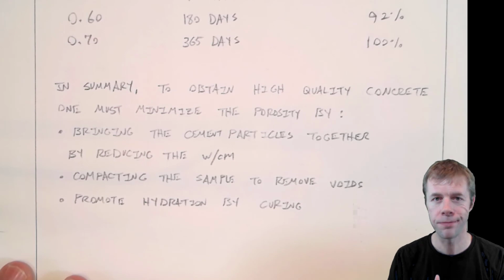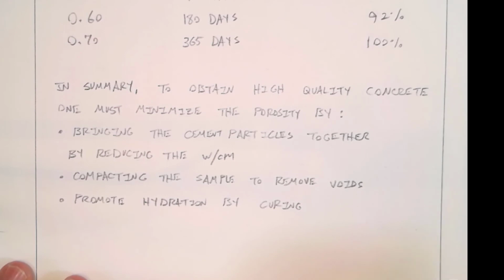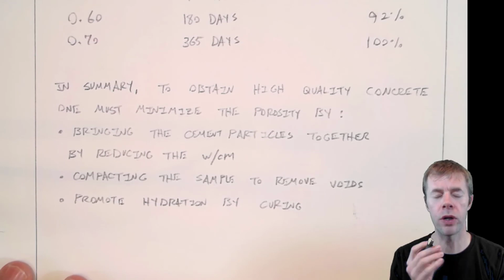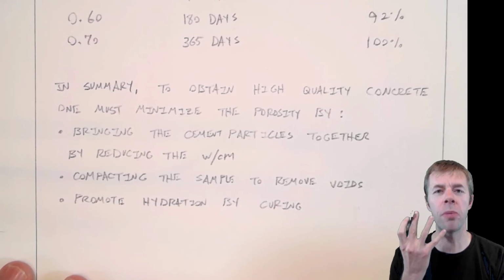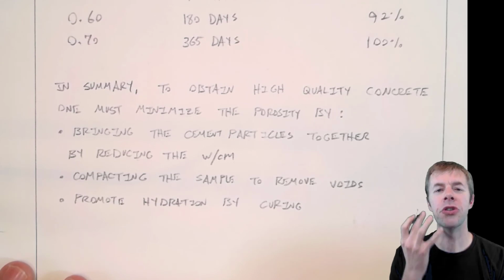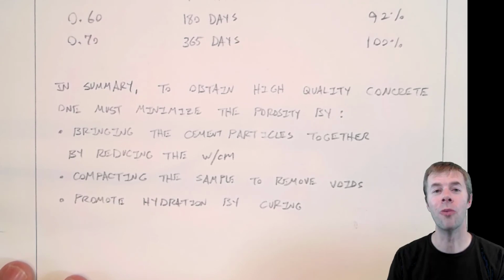But is that enough? Nope, sadly not. You've got to promote hydration by curing the concrete, keeping it moist, keeping it warm, letting it hydrate, letting that structure grow. And you're not going to make the concrete that you hope to, the best you possibly can, until you do all 3 of these. And you do them well.